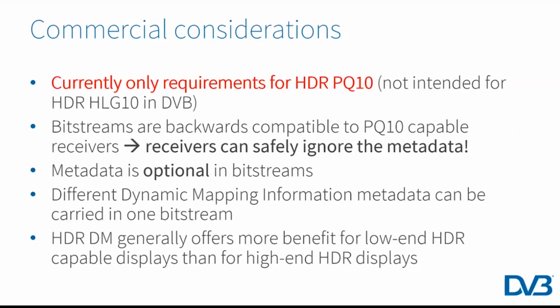So that a consumer with an existing PQ10 receiver without the capability to do anything with the dynamic mapping information would still receive the same image as they would have done before the introduction of the system. So the bit streams would be completely backward compatible to existing or future baseline PQ10 receivers.